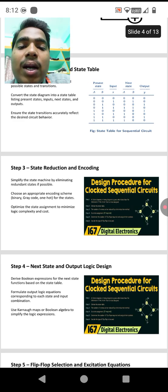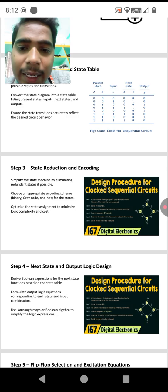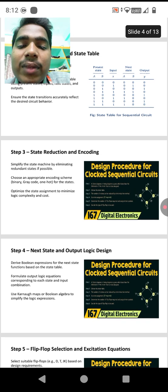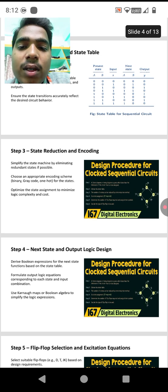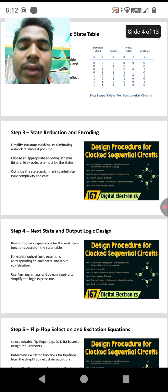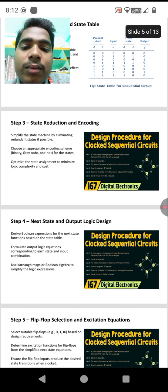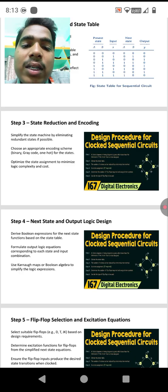Step 3, State reduction and encoding. Simplify the state machine by eliminating redundant states if possible. Choose an appropriate encoding scheme: binary, gray code, or one-hot for the states. Optimize the state assignment to minimize logic complexity and cost. These are the design procedure steps for clocked sequential circuits.